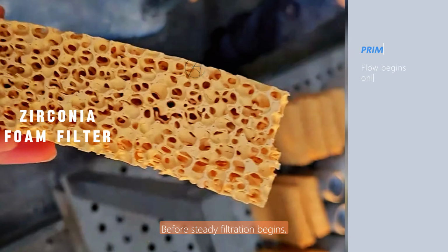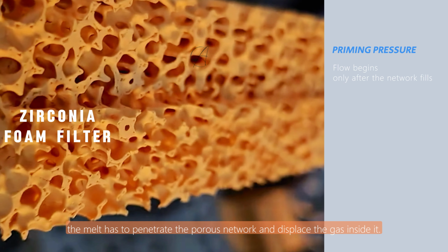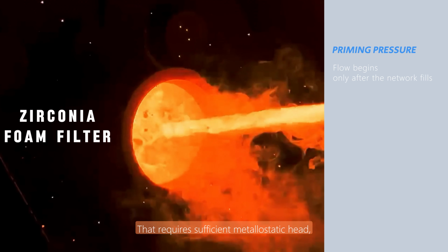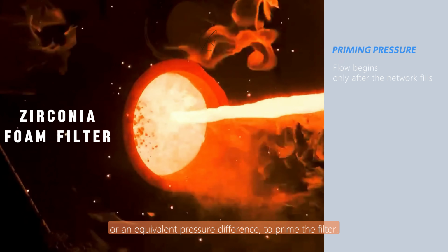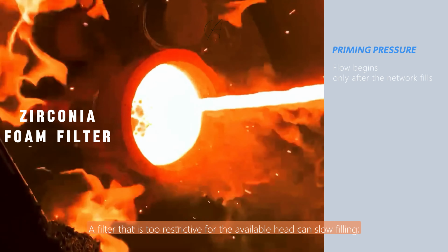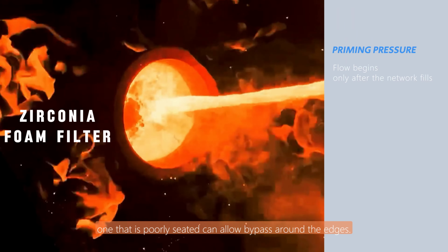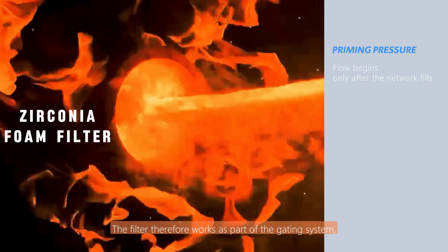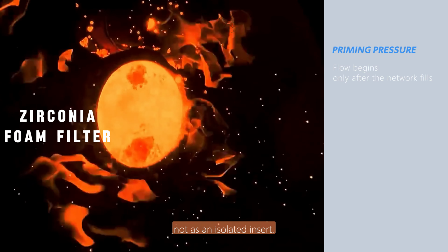Before steady filtration begins, the melt has to penetrate the porous network and displace the gas inside it. That requires sufficient metallostatic head or an equivalent pressure difference to prime the filter. A filter that is too restrictive for the available head can slow filling. One that is poorly seated can allow bypass around the edges. The filter therefore works as part of the gating system, not as an isolated insert.